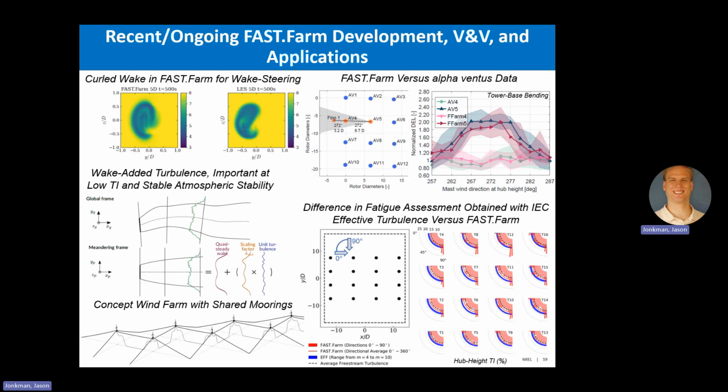This is showing, I think, the turbulence intensity at all 4 turbines as a function of wind direction. And you can see when flow is going from, say, bottom to top, the upstream turbines are seeing basically the same thing, but downstream you're seeing higher and higher TI. And you won't get that directionality effect through the original model.